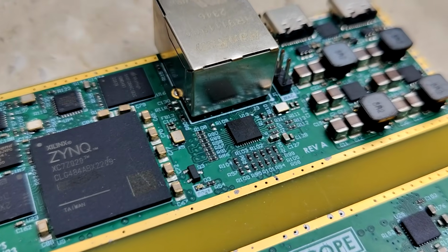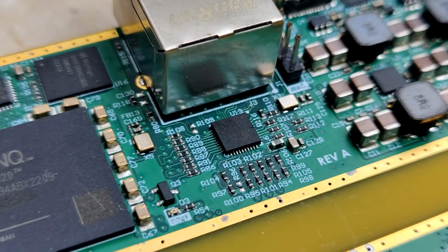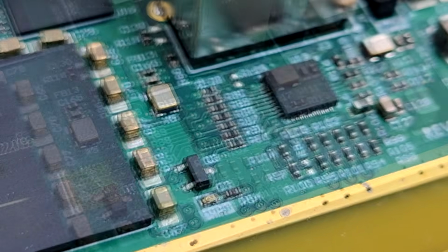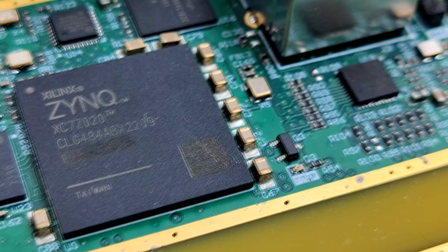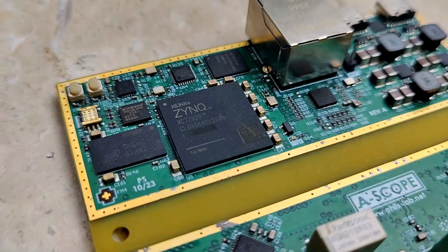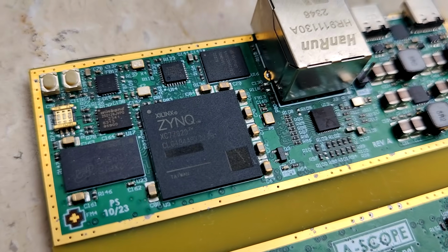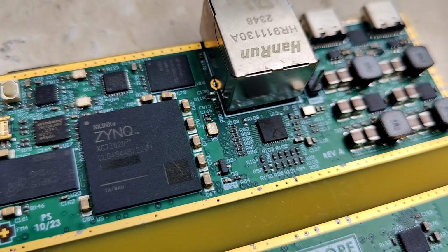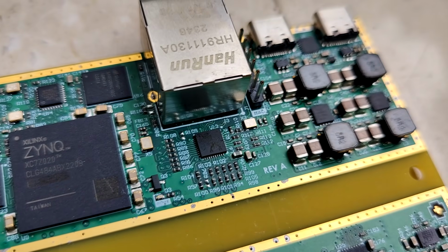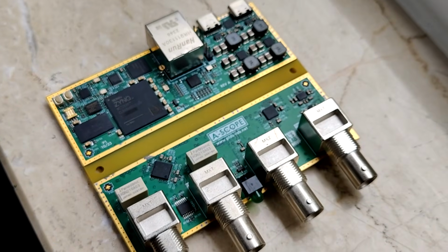In this video, we'll cover the essentials of Gigabit Ethernet hardware design. We'll start by looking at the components involved, such as MAC, physical layer, magnetics, and connector, see how these are connected together, what interfacing standards we will be using, what signaling, for example RGMII, MDIO, and so on, how we might be selecting certain components, and what these components look like in detail.